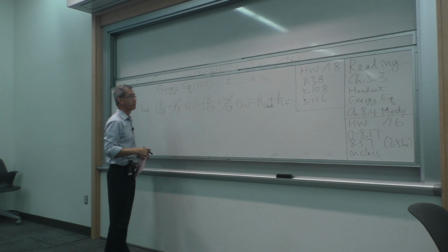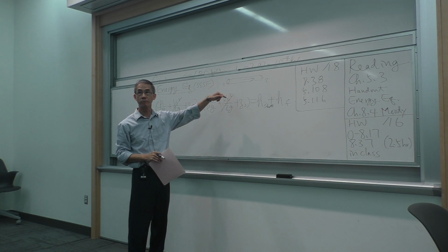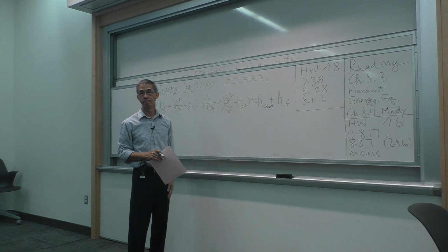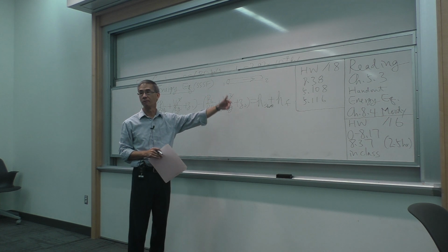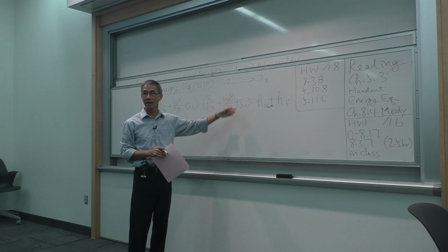Now, you may say, well, there is not enough pressure to push the flow from 1 to 2. Then the velocity of the flow may stop in the pipe. And that will happen if your pump power is not enough. But is that a steady problem? No, it's not, because what's coming in is not going out. That's a transient problem. That's where the engineer turned on the pump, the flow started, halfway to stop.